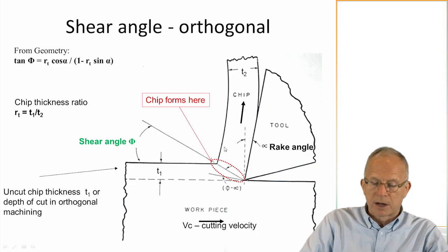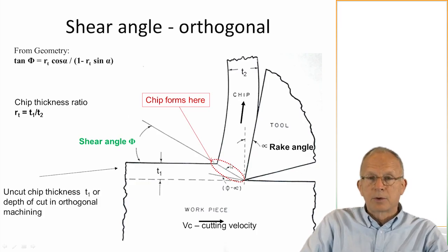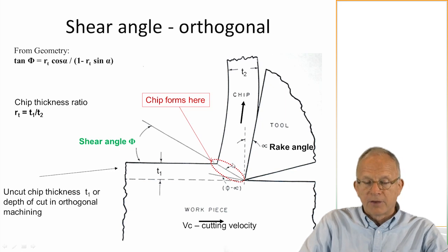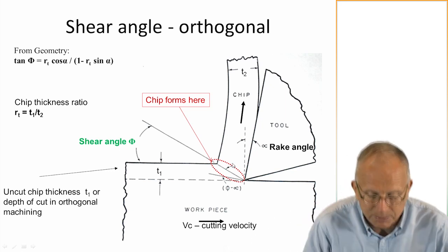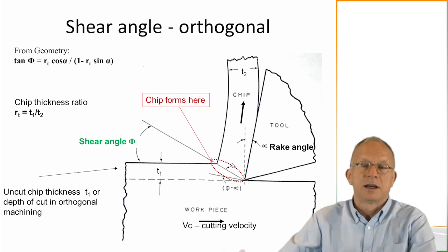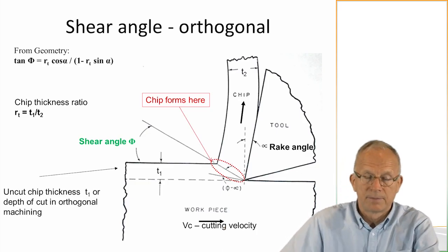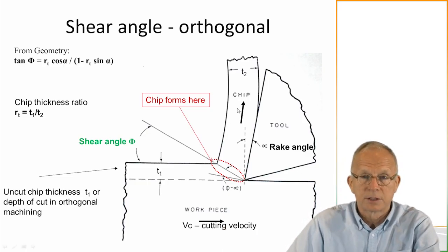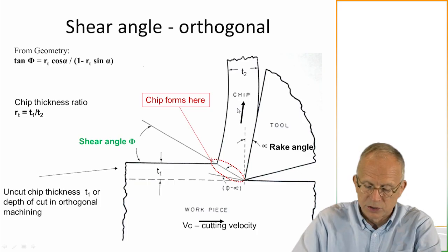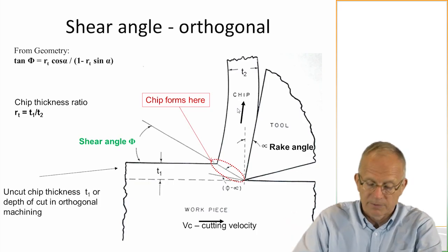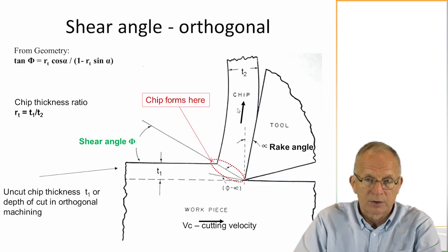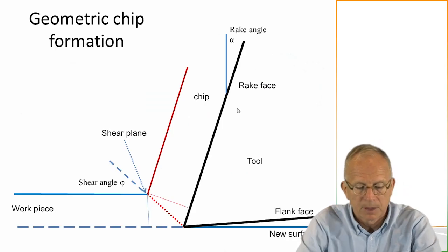It doesn't matter what I'm cutting. This could be a knife scraping butter, and the same equations would apply. In fact, the same sort of kinematics apply, and if you're scooping ice cream, you're creating chips, and it's also shearing, and you can see the shear lamella forming with that, or scraping butter, for example.